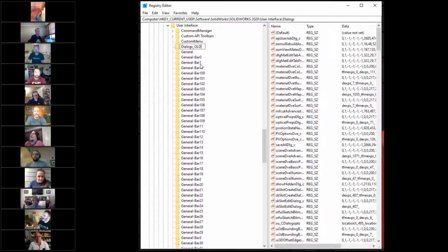What's happened to me is it looks like SolidWorks is locked, but really there's some dialog box looking for an input from you, and you don't see that because it's on a monitor that doesn't exist. So you think you're locked up and you're really not. So if it's a dialog box, ask yourself, could this be a dialog box that I'm not seeing because it's hidden on some unknown, non-existent monitor? I'm pretty sure it's definitely the Windows key.